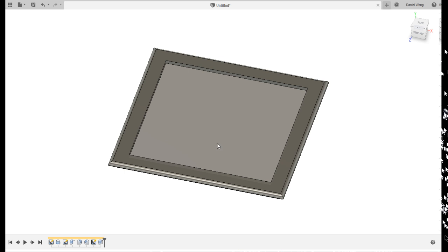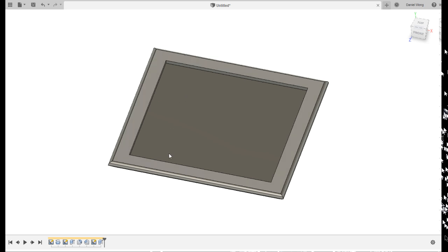In order to do that, we need two things, and it's two sketches. The first one is the cross-section of our cut, and I hope everyone knows what that means. In my case, I'm just going to do a very simple arc, like a circle segment, as my cut. I can cut that along the second item we need, which is a path that we need to draw it around. In our case, it's just going to be a line that follows the boundary along a middle path along this shape here. So, is everyone ready to go?